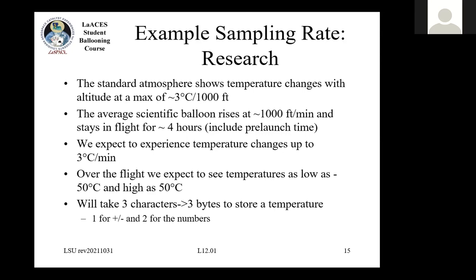Okay, so now I need to know, how quickly is the payload going to be rising through the air? Usually that's around 1,000 feet per minute. And how long is the flight? Well, the actual flight is usually something like 2.5 hours, 3 hours, but we want to build in some extra time because we're going to get turned on the ground and we may be sitting there for a while. So we'll just say that we want to make sure we have enough data storage and capability for 4 hours of data.